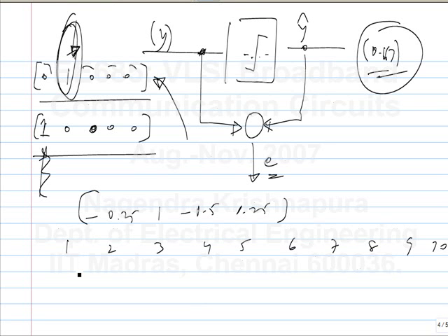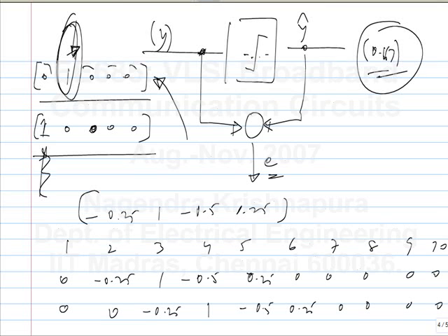There is an ambiguity. If you have 0, minus 0.25, 1, minus 0.5, 0.25 and all these zeros, it's a good equalizer. If you have two zeros and minus 0.25, 1, in this case also the eye opening will be the same, right? It's simply delayed. That's all. So unless you restrict the range of coefficients, there is some ambiguity in the convergence as well. Okay. So in practice, you always restrict the values of coefficients so that you can guide the convergence.